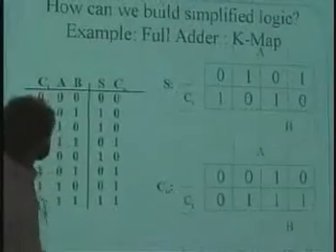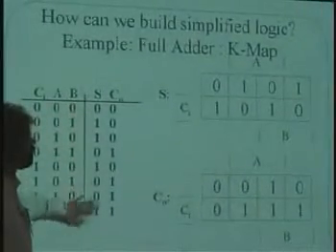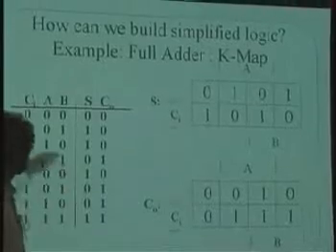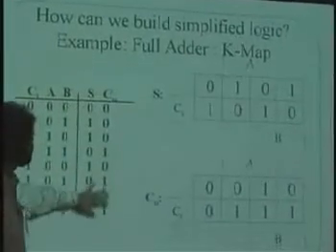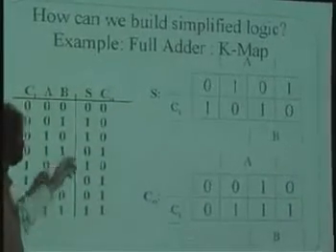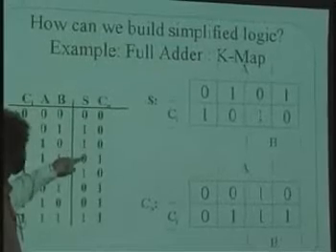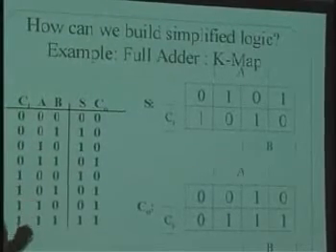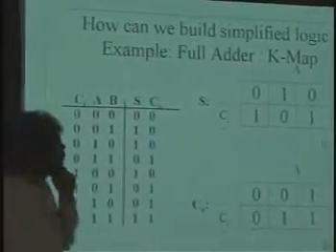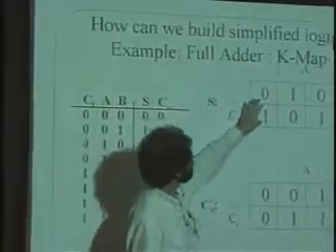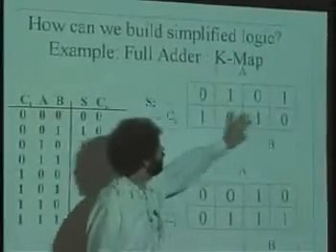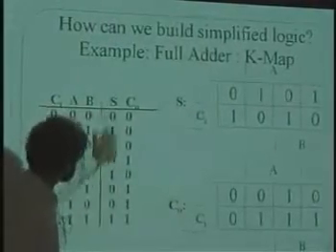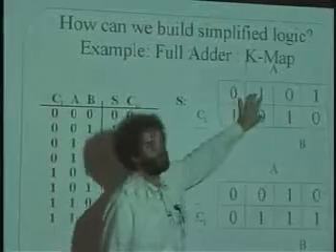Here's the idea. Instead of showing the table like this, or even with the lines switched like that, which would have been a great idea, we rearrange the order of these bits to more closely show which ones and which zeros correspond to changes in the input where only 1 bit is changing at a time. So I'm going to label a table here of 8 bits. Here's 8 bits that are going to be for S. These are the same 8 bits as there are over here.